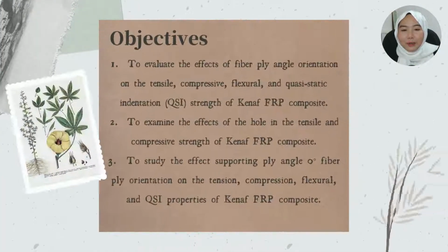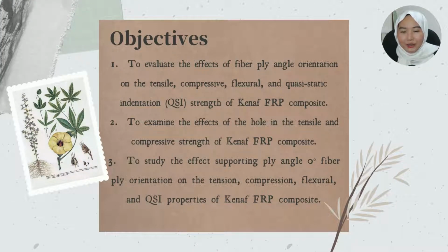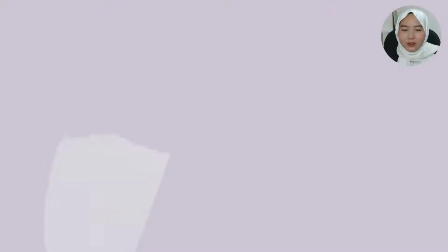The objectives of my project are to evaluate the effect of fiber ply orientation on the tensile, compressive, flexural, and quasi-static indentation or QSI strength of Kenaf FRP composite, to examine the effect of a hole on the tensile and compressive strength of the composite, and to study the effect of supporting triangle 0-degree fiber orientation on tension, compression, flexural, and QSI properties of the composite.